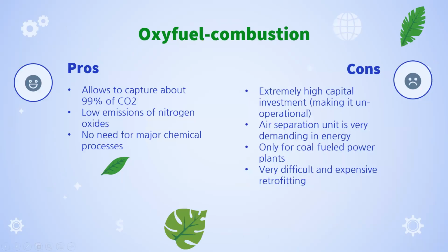Moving on to the pros and cons. This oxy-fuel combustion, although it seems a lot more advantageous since it allows the capture of about 99% of the CO2 and very low nitrogen emissions, has a very high investment cost, making it almost impossible, a non-viable solution, as well as a very high energy penalty since the air separation unit is very demanding on energy.